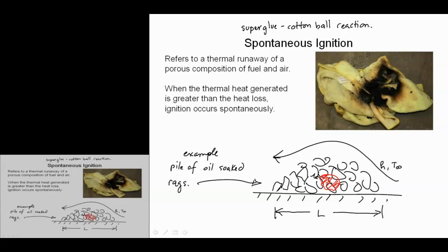But what happens, of course, is when you imagine a relatively large amount of an oxidizing system, where that system is more and more isolated thermally from the environment. Then with this high resistance to heat loss, the oxidation process is generating heat, is incapable of releasing that heat to the environment, and increases the local temperature within the system, which accelerates the oxidation rate, which then in a feedback process causes this thermal runaway. Okay?